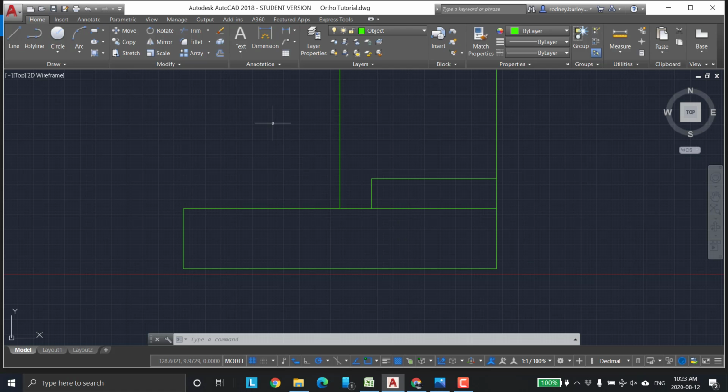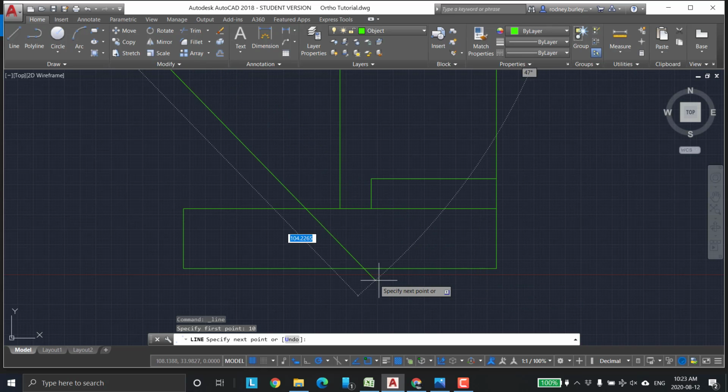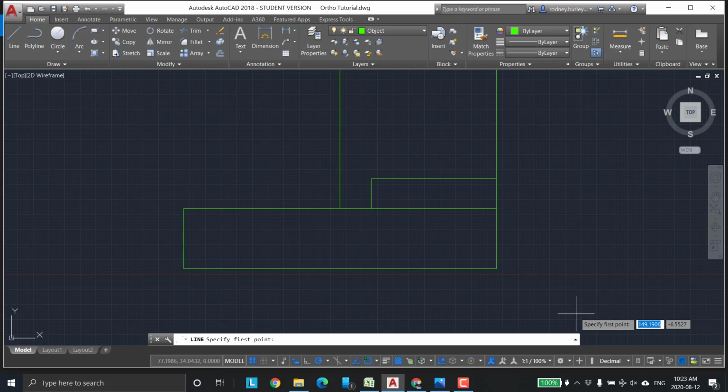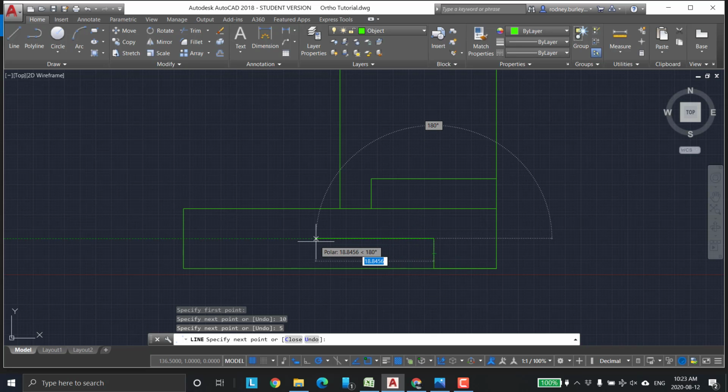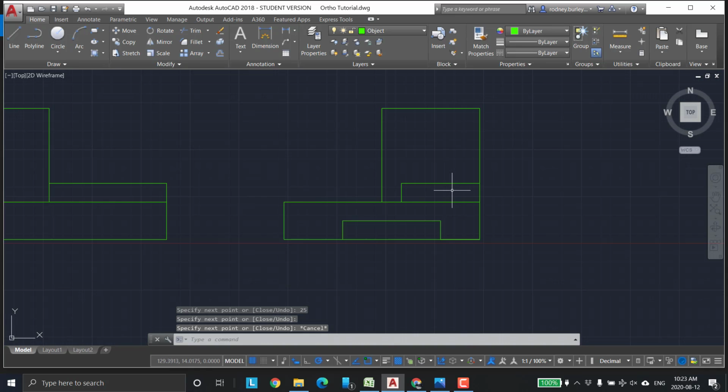And so how do I do that? I'm on the object layer, create a line, bring the line down across this way. So walking it that way, it's 10. So it's locked in down at 10 now. And line it up this way, 10, enter. So it's drawn down at 10. And then we're going to go up at 5, enter. We're going to make it 25 wide. And we're going to go back down and grab it here. So that feature is now drawn in.